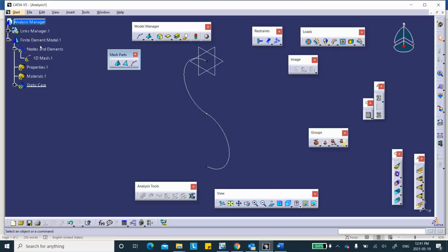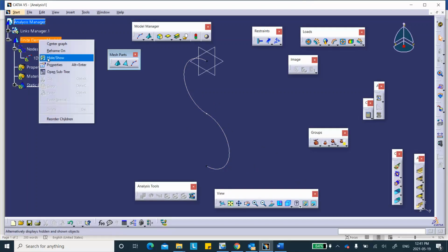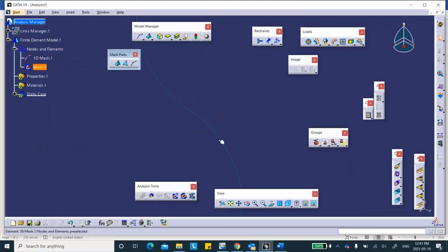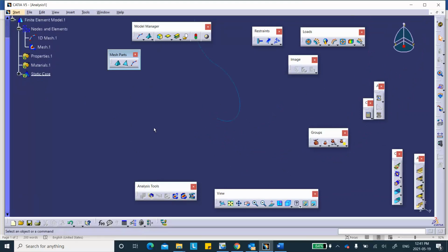Okay. So let's check our mesh. Put the cursor there, right click, mesh visualization. Notice that you go in there. So here is an element. Notice that because I use parabolic, there's element 65 and the node numbers are 3, 24, 22, and 45. There is element 66 and the node numbers are 45, 23, and 46. If you ask me, should I use parabolic or linear? If you're not told anything, do whatever you want. We don't care. All right, so this is fine.